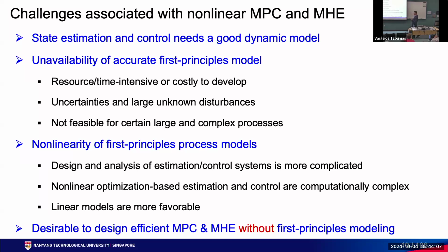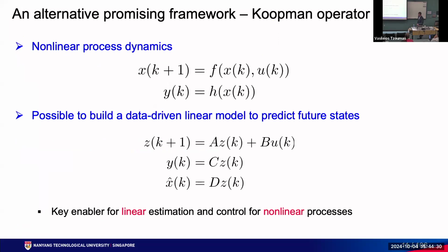Okay, so based on this consideration, we would like to opt out of first principle modeling, and indeed it is favorable to try to leverage linear models to account for the dynamics of nonlinear processes, right? So this is the motivation. We would like to build efficient MPC and MHE designs without performing first principle modeling. Okay, so this is the idea. We have nonlinear process dynamics, but we would like to build a linear model.